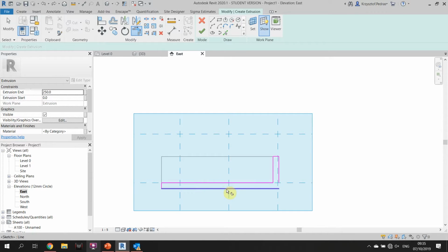And we can click on the one on the bottom, because right here we have a hole that we want to fill out. We can click the line on the bottom, and we can click the line on the side. And after we click it, you can see that it trims the corner, it extends it to the point that we specified. Let's go again. I'm gonna undo that. If you click on the option of extrusion, we click the line on the bottom, we click the line on the right, and it extrudes to the corner.